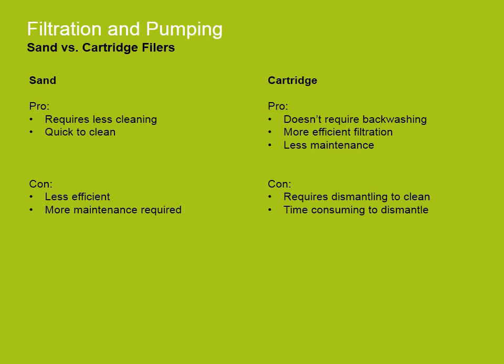Cartridge filters do not need to be backwashed, meaning they don't waste anywhere near as much water cleaning the filters. Instead, the filter is pulled apart and the fabric of the filters is rinsed to remove impurities. This is a time-consuming process compared to backwashing a sand filter, but reduces the cost of refilling the pool. Generally, cartridge filters are more efficient than sand filters, though this is obviously dependent on size and quality. However, the cost of replacing the filters in a cartridge model can be as much as $200 per filter. In general, the efficiency of a cartridge filter negates whatever difficulty is incurred in cleaning or replacing the filters, and they are frequently preferred to sand filters.